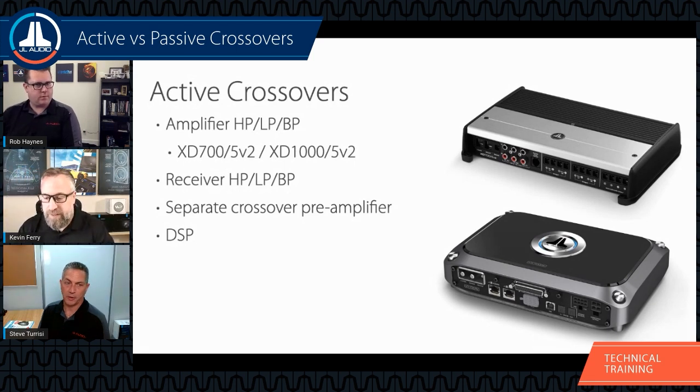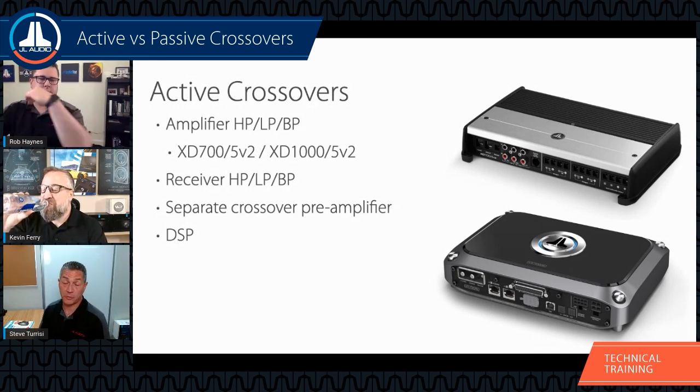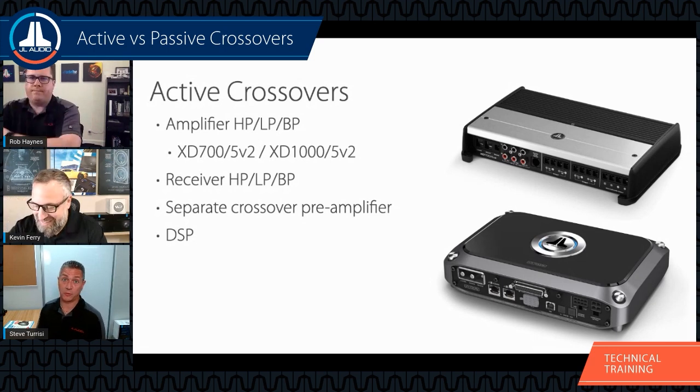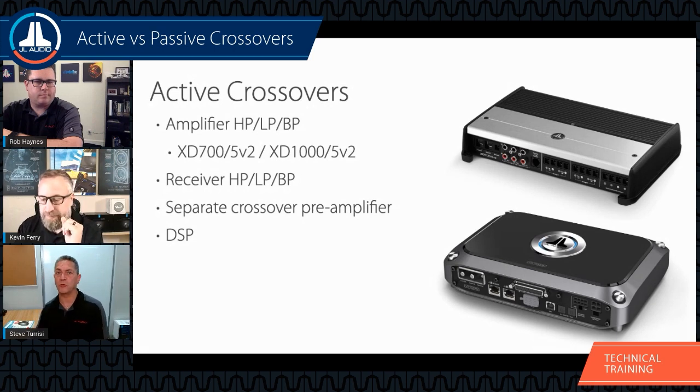All right, I got to do it here. I got to say it. I really don't like the idea of having filter controls like that in a source unit, because it's a tuning setting. It's not something you're going to change on the fly. If the system's been set up and designed properly and tuned properly, you should never really need to change your filter frequencies.